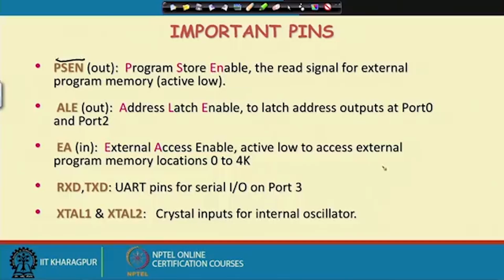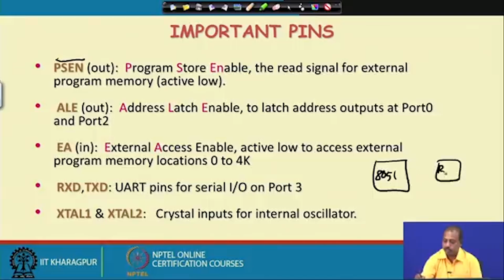ROM interface. So, if this is your 8051 and you have connected the external ROM here, for the ROM I will have that read bar line. That read bar line should be connected to the PSEN bar line of the 8051. Okay. So that is there.